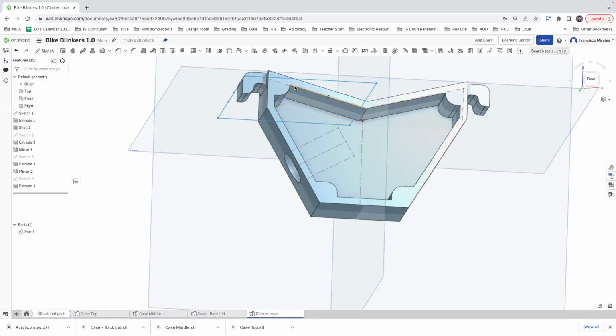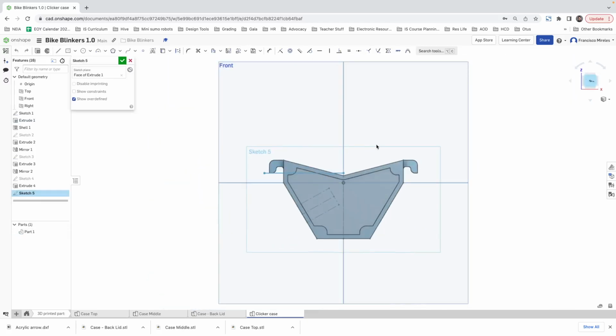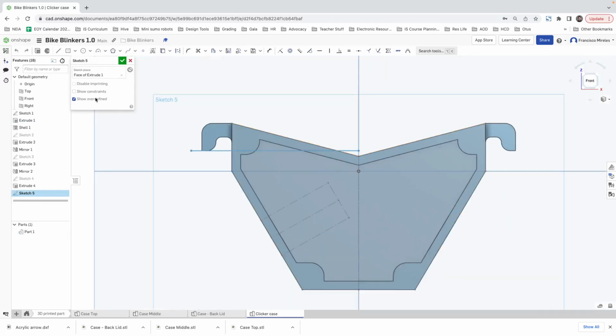So now, again, a new sketch here. And I can look for the center that is concentric to this one. Do you see that? I set circle and then I touch on this, just touch it, just don't click on it, and then you look for this point, which is the concentric point to that part of a circle. And then here we said, before I forget, 4.8, 4.8.